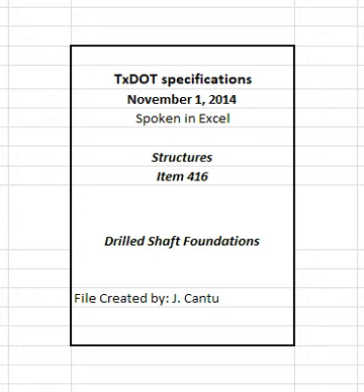3.1 Excavation. The plans indicate the expected depths and elevations for encountering satisfactory bearing material. Excavate as required for the shafts through all materials encountered to the dimensions and elevations shown on the plans or required by the site conditions. Removal of man-made obstructions not shown on the plans will be paid for in accordance with Article 9.7, Payment for Extra Work and Force Account Method.